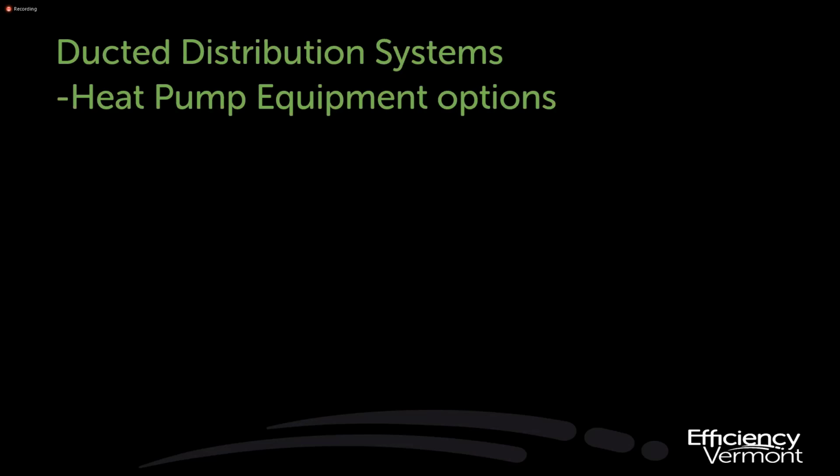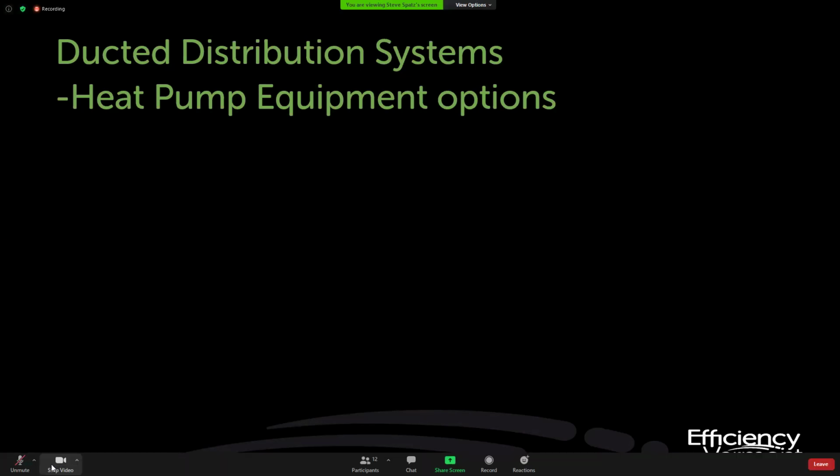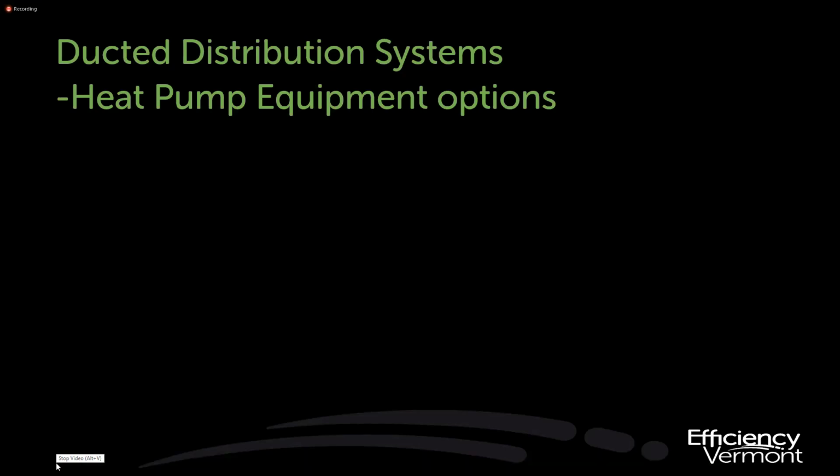That's policy that's coming into play, but it's also a practical implication of the building performance that we're getting now. We're getting buildings that have much smaller heating loads and cooling loads, and fossil fuel equipment often puts out more heat than the building needs.